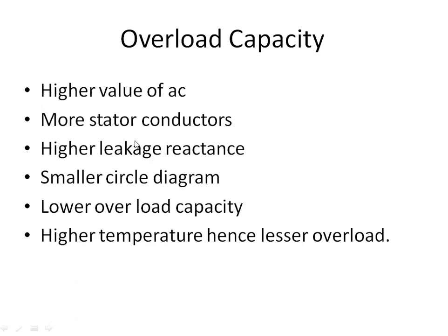It can also be looked at from the other point of view that for higher temperature rise, we will require lower ampere conductors as discussed. So if the motor rises to a greater temperature, then it cannot take up the additional overload capacity, even if it cannot take up the full load capacity. So in order to have more overload capacity, we must select the value of ampere conductors which is comparatively lower.